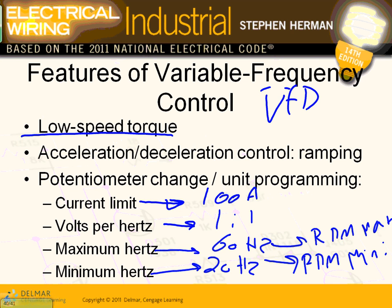So these are the things, guys, when you drive the VFDs. We don't have VFDs in this room. When you drive them, you have to go there and adjust and set these limits. So I can't go higher than 100 amp. The voltage is going to go 1-to-1. So if the voltage is 480, then 60 hertz. The voltage 240, 30 hertz. So you reduce the frequency.